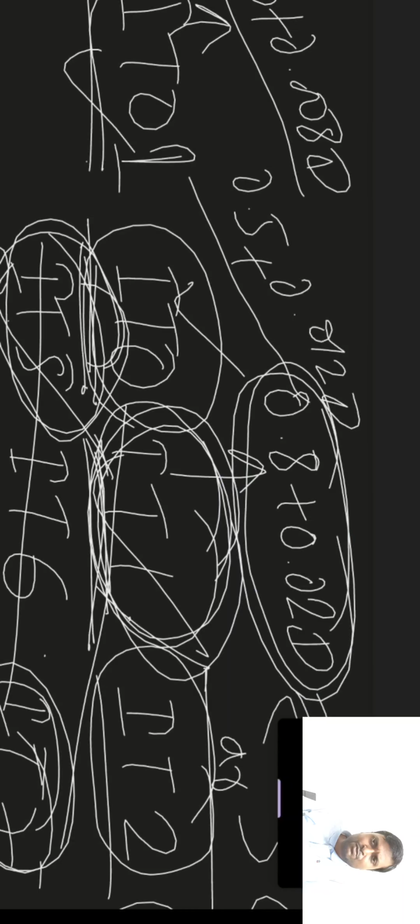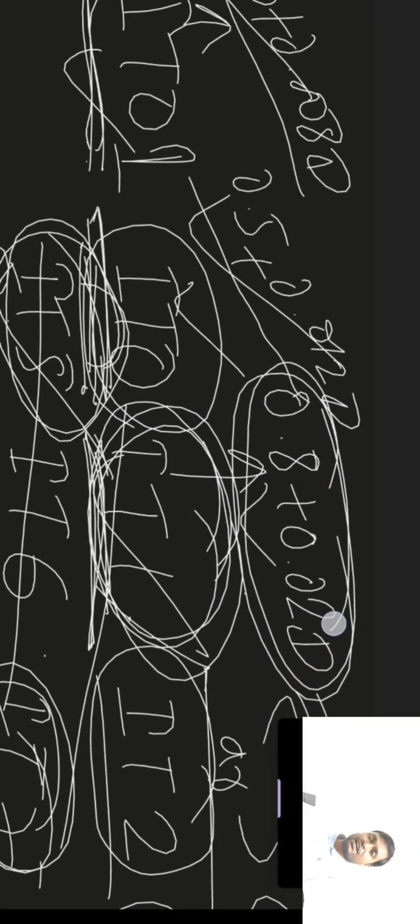This is the initial value which is being multiplied with a particular value R to get the next tolerance grade value. But these three, IT01, IT0 and IT1, are having a specific formula, and these are known as empirical formulas. So IT01, IT0 and IT1 have empirical formulas.